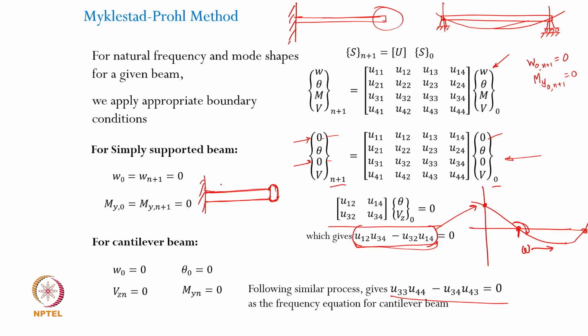Again, this entire process is an approximation anyway, right? So you will be discretizing it, and I can have the last end element like this. If this distribution is not regular and it is small in size, but there is enough additional mass there, I can lump the mass of this entire segment into the mass of this particular segment here.